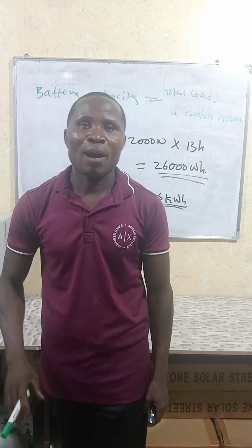Now, considering the region we are in, especially in this country, we are close to the line of the equator. Our peak sun hours are considered to be 5 to 5.5 hours per day. And that is why we are looking at the total number of panels you will buy at the market. How many panels of 460 watts are you going to buy? We are using calculation to figure them out so that we will not make a mistake.